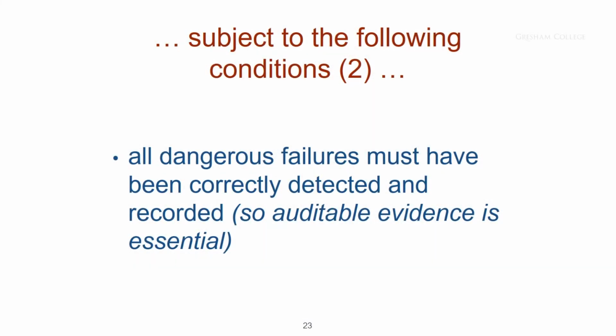Second obligation is that you do actually need to know whether it's failed or not in your 10,000 hours or however long of previous experience. So you need to be confident that you have managed to detect all unsafe failures, and that you've got evidence that you've done that, and that you have collected the logs and analysed them and so on. So auditable evidence becomes essential.